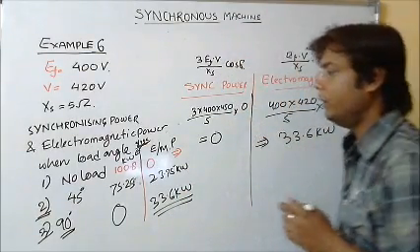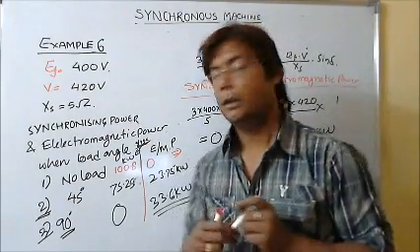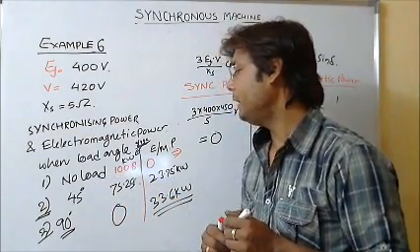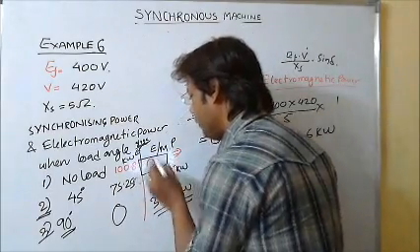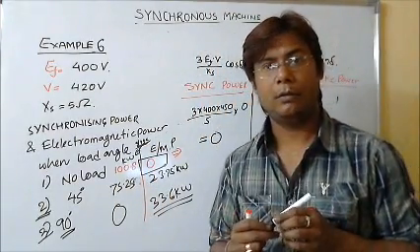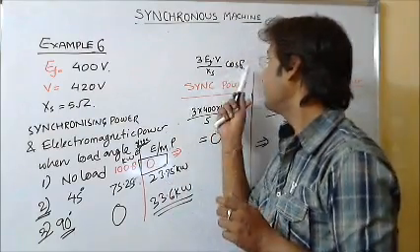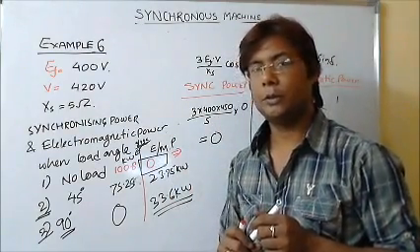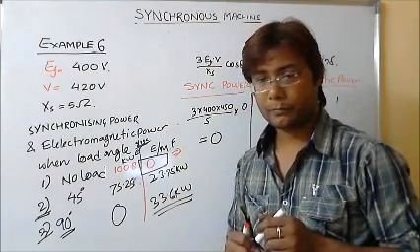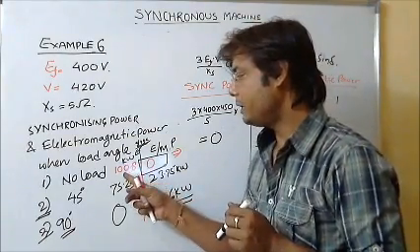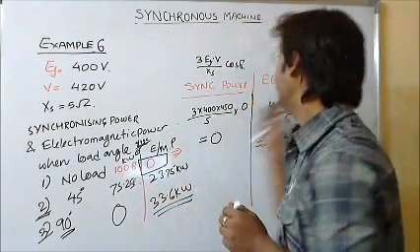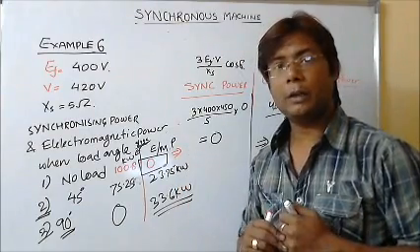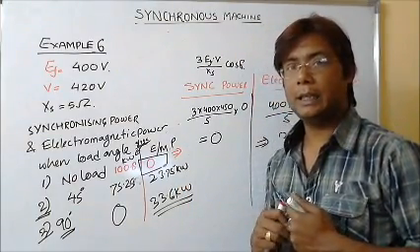So I get all the six answers. At no load, the synchronizing power is 100.8, because cos 0 is 1. And sin 0 is 0, so I got the electromagnetic power as 0. So no electromagnetic power is generated when the delta is 0.